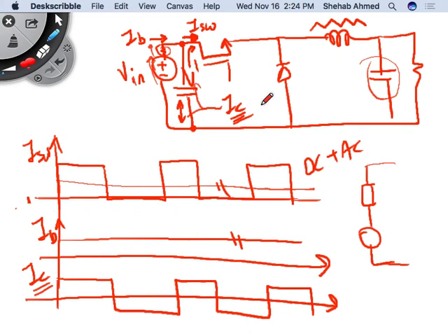And if you put a capacitor, it will absorb all the ripple current flowing through there and allow that capacitor to maintain a fixed voltage, or a voltage with less ripple, however you want to call it. So capacitors at the input or output are the same. Do you see why we added one here? It wasn't clear. I didn't explain too much before, but I hope it's clear now.